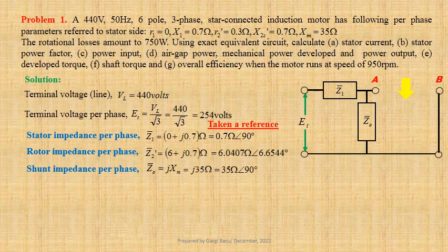Let us now calculate Z0 plus Z1. Using values we get 0 plus j times 35.7 ohm. This may be written in polar form as 35.7 ohm at an angle 90 degree. Now we shall determine Thevenin's voltage.